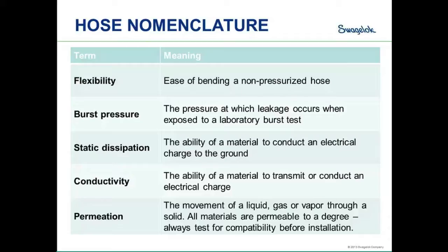Burst pressure is usually done in a controlled environment in a lab. We do that to understand what the catalog rating or industry rating should be on the hose. General rule of thumb is a 4-to-1. So in other words, in a lab-controlled environment, if a hose was to burst at 10,000 psi, it would go to market with a 2,500 psi working pressure.